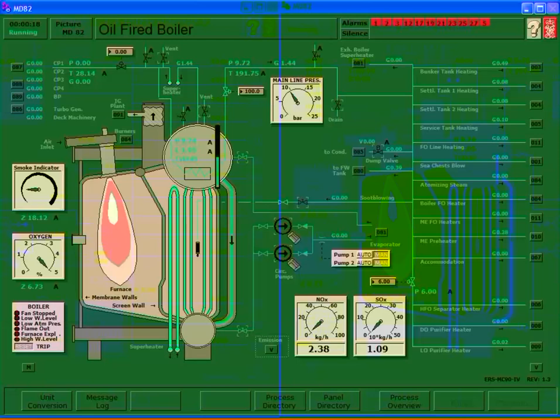So you don't want superheated steam for saturated services, for heating. Absolutely do not want it. So if you see a superheater, go find the steam turbine. You only have superheated steam for a steam turbine, because a steam turbine will directly convert that heat into usable power.